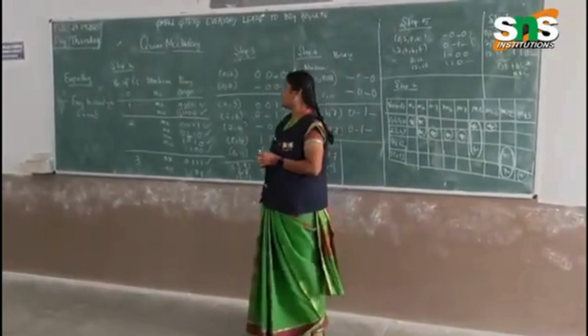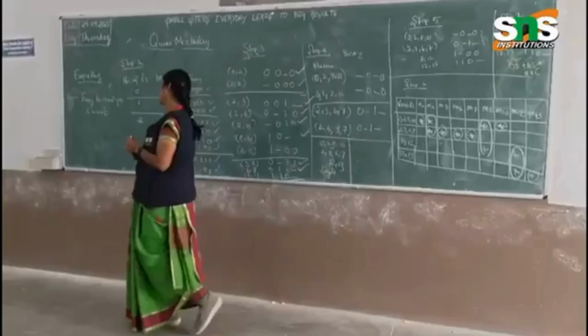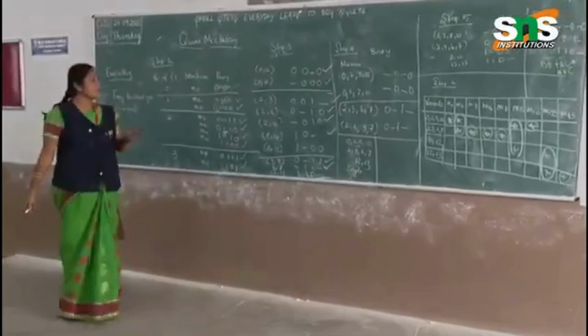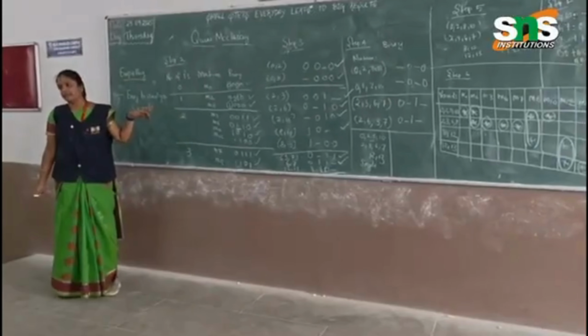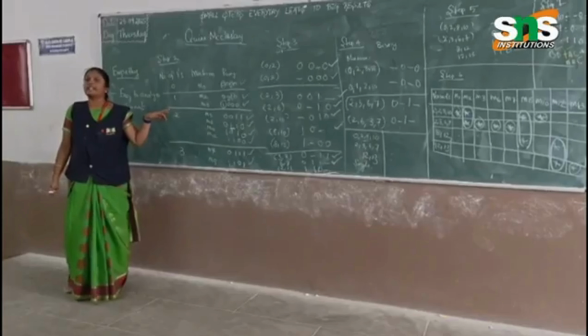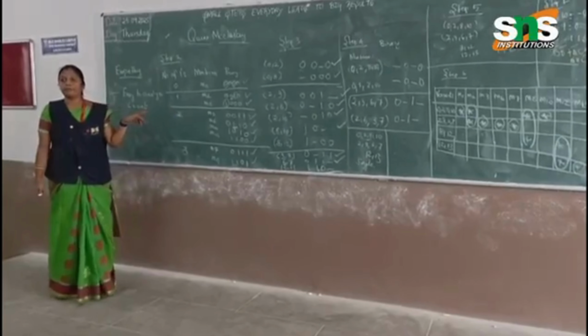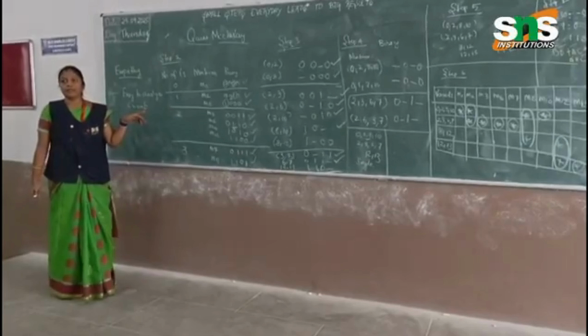So let us have a small problem. Reduce the Boolean expression: summation m of 0, 2, 8, 3, 6, 10, 12, 7 and 13, where m means minterms. Minterm means SOP, sum of products. In the Quine McCluskey method, there are 5 steps.